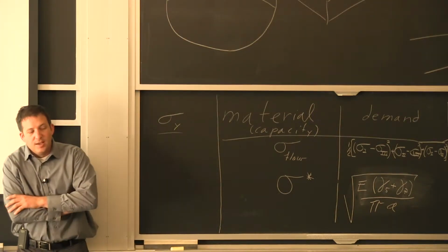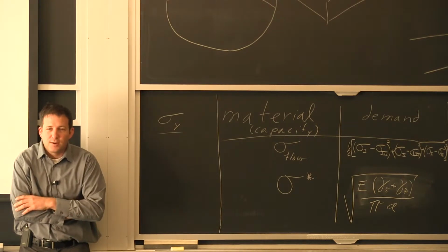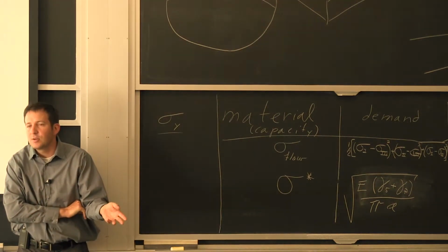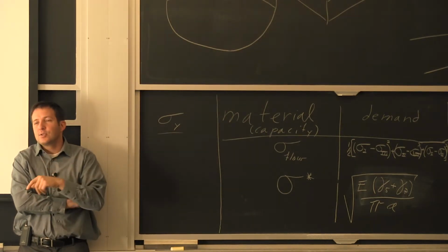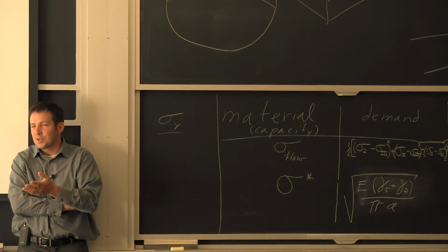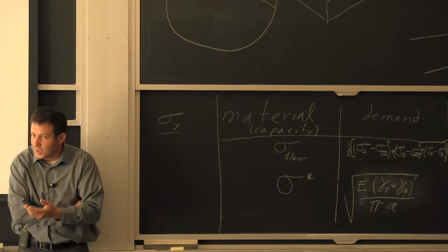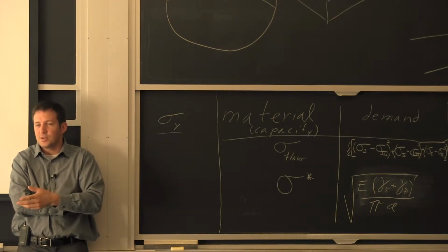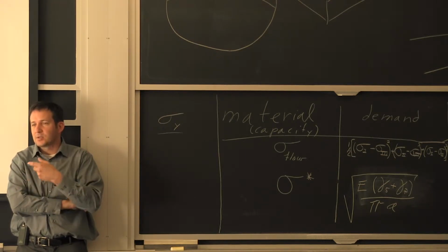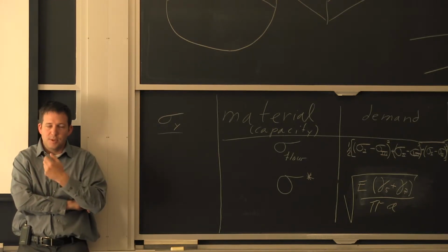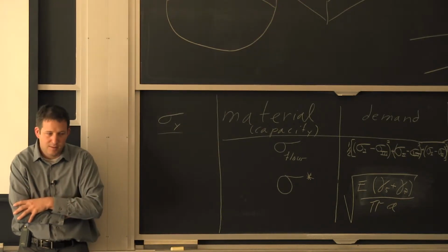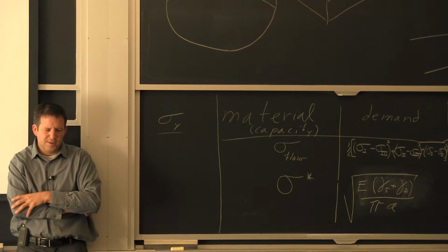And because you have a very nice surface finish, and some of them can be single crystals, you can go a little beyond that 40% of yield strength that we talked about, but not a whole lot, because eventually you would start a crack. It's just going to take longer. And that's why you limit the life of these components by saying, okay, it's been 5,000 hours.